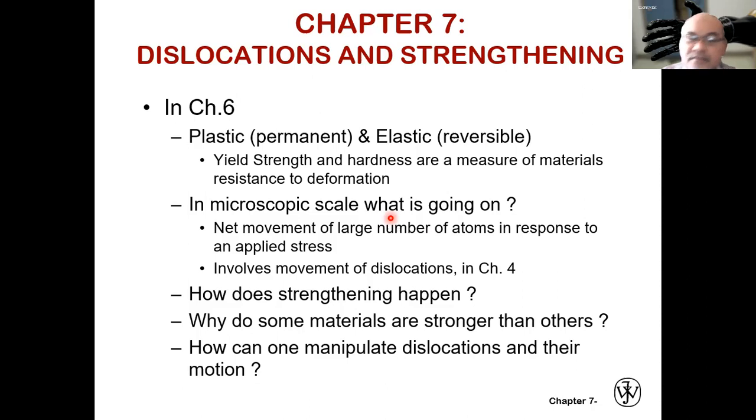But later in the strengthening mechanisms, you can also have a mechanism where these defects or dislocations can be made to be entangled with each other. So they will stack and lock to each other, which will strengthen the material so that upon the application of stress, they cannot deform as easily as before. So it means that the yield strength is made to increase.